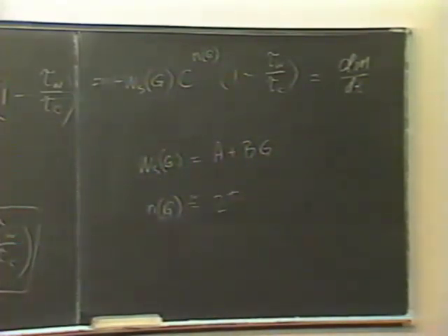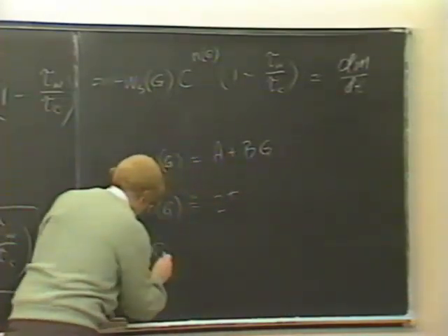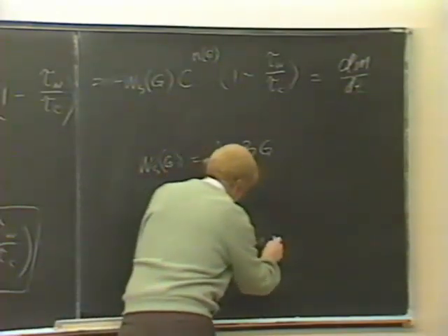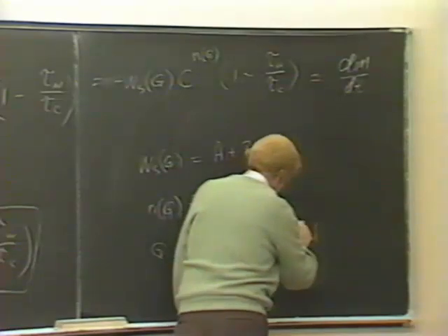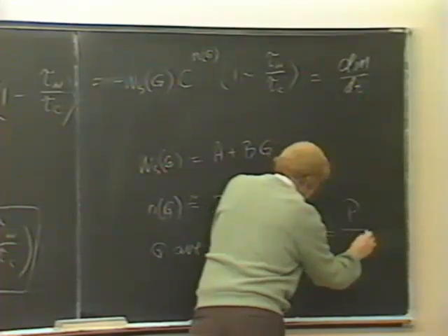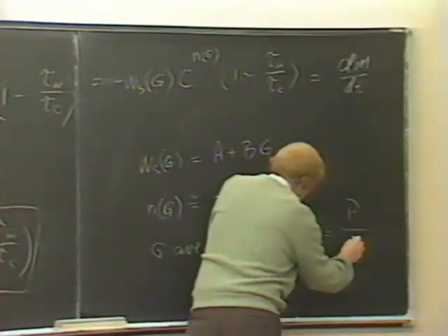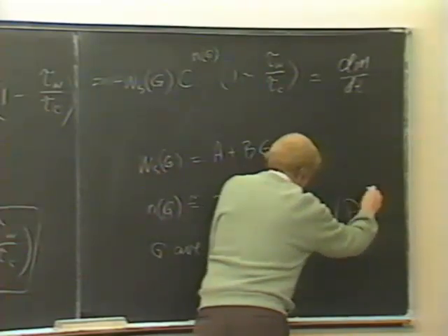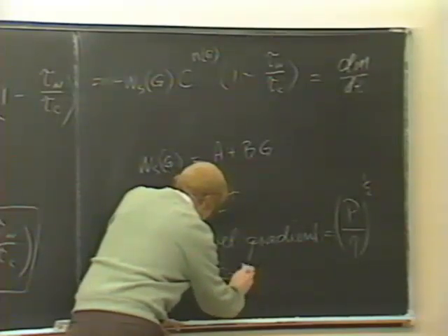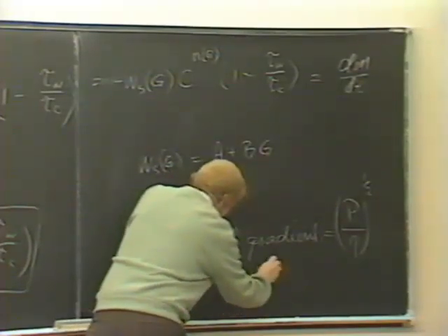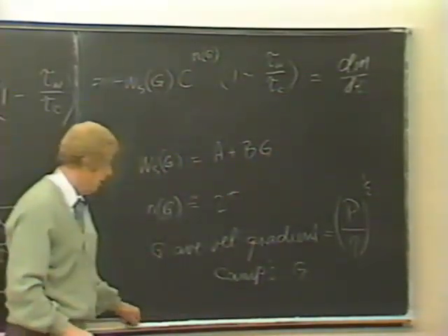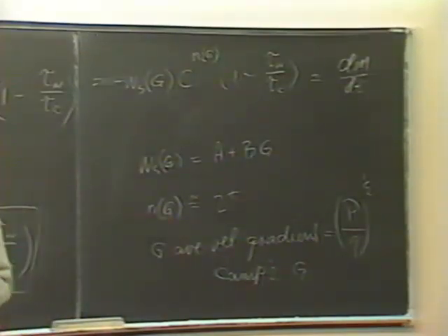I mean, in a marsh, for example, in calculating the rate of rise of a marsh surface due to deposition, you can take core samples and date the different elevations from cesium-137 or lead-210 or some dating method, and determine the rate of deposition over time, and calculate using the model, find the concentration that gave you that same rate of deposition, and it turns out to be typical of what you find in near-shore waters.